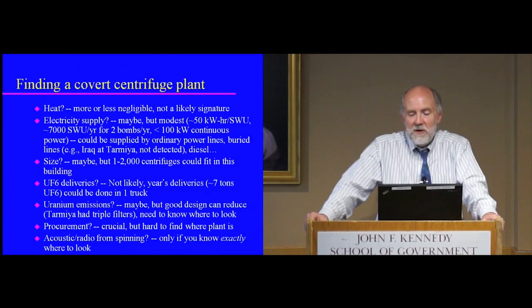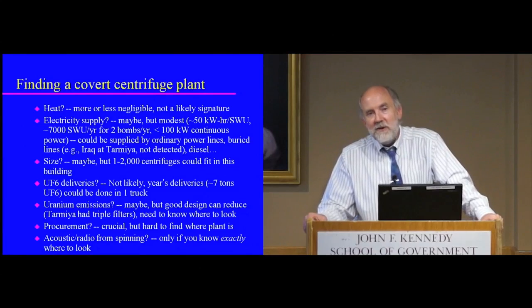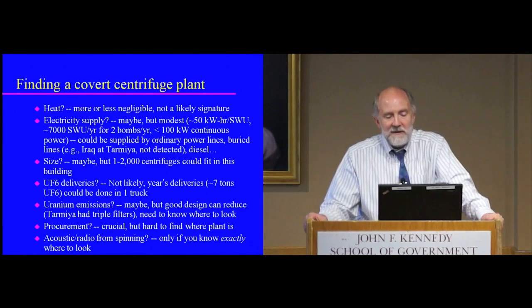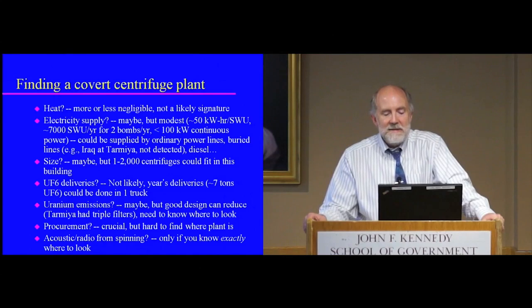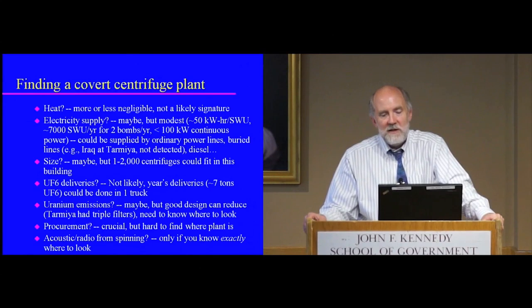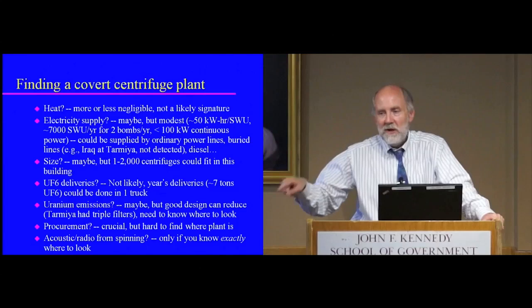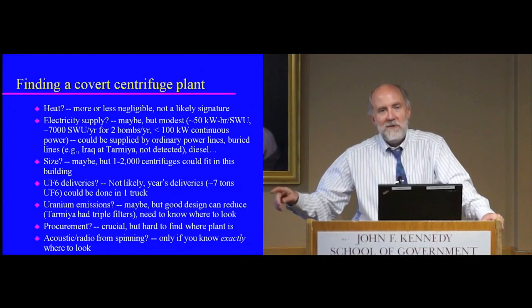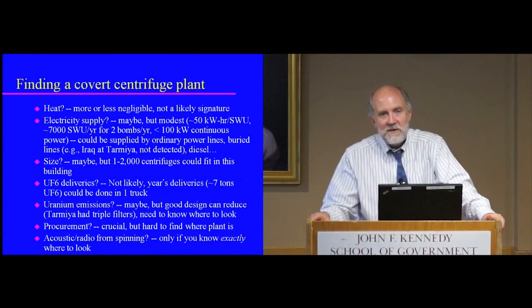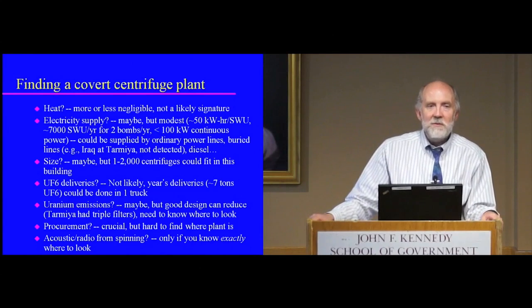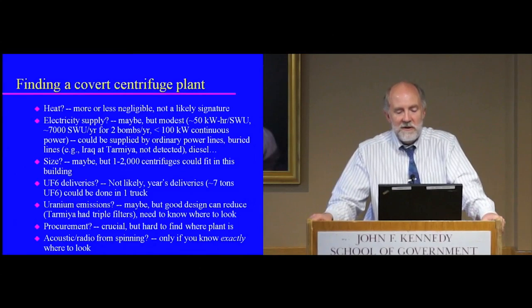Size, pretty small, could fit in this building. There are lots of buildings that are big enough. Deliveries of uranium hexafluoride, not likely. You could conceivably deliver all of a year's supply in one truck. Uranium emissions, conceivable, but as I just mentioned, if you have good filters, it's hard to find unless you really know where you want to look, so you can get within a few hundred meters of the facility and not likely find it. One of the Iraqi facilities at Tarmiya had triple HEPA filters to try to make sure nothing got out.